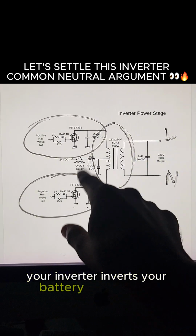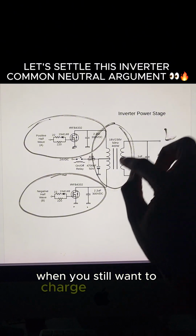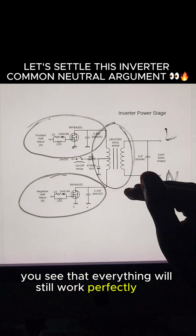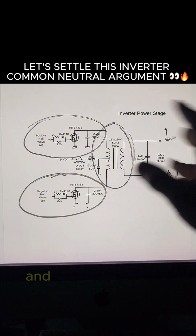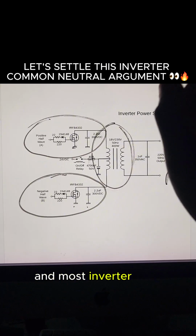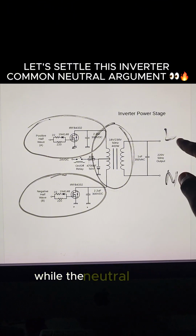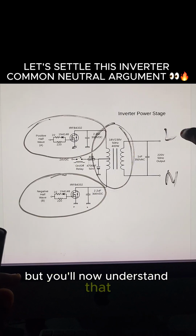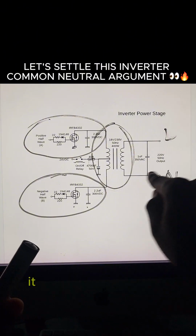Your inverter inverts your battery power to AC and it gives it out through these two terminals as live and neutral. When you still want to charge this inverter, it will still go back through here. So even when you switch these two, neutral goes here, live goes here, you see that everything will still work perfectly fine. The only thing is, because there are also some parts we're not discussing which has to do with the switching of the inverter and the lights, most inverters only switch the live line, which will not mean that the live will be on the neutral line that didn't switch. But that's not the case we are discussing here. But you'll now understand that even when you switch these two, nothing will still happen. And when the input comes in, it is still that same neutral.